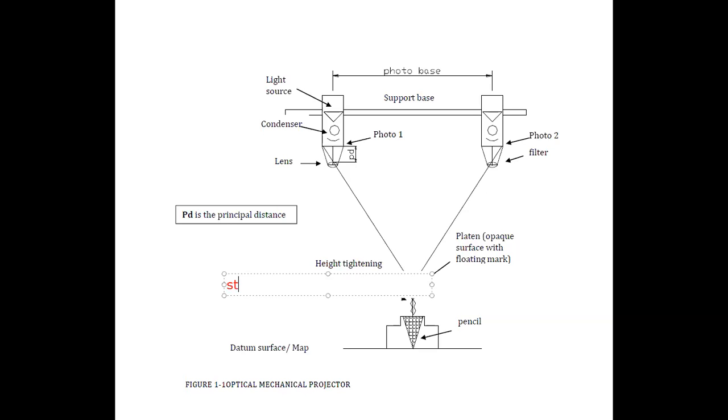The stereoscope was some kind of instrument with some mirrors and binoculars that allowed us to place two photographs, align them along the flight line, and then observe in 3D the two images now fused together. It created a 3D impression of the ground or the project area.